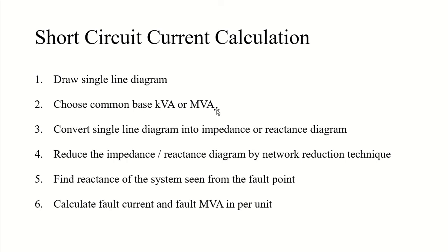And now, how do we do this analysis? The analysis is done in order to decide the rating of your circuit breaker, and also the current-limiting reactors, right?